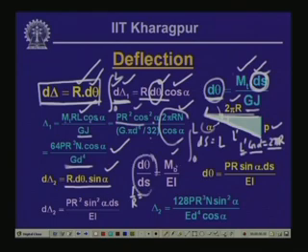So, d theta by ds equals M by E I, where M suffix b is the bending moment, and therefore, d theta is equal to Mb ds by E I. So, in r d theta times sin alpha, if we replace d theta with Mb ds by E I, and if we integrate that, then d delta 2 becomes p r square sin square alpha ds by E I.